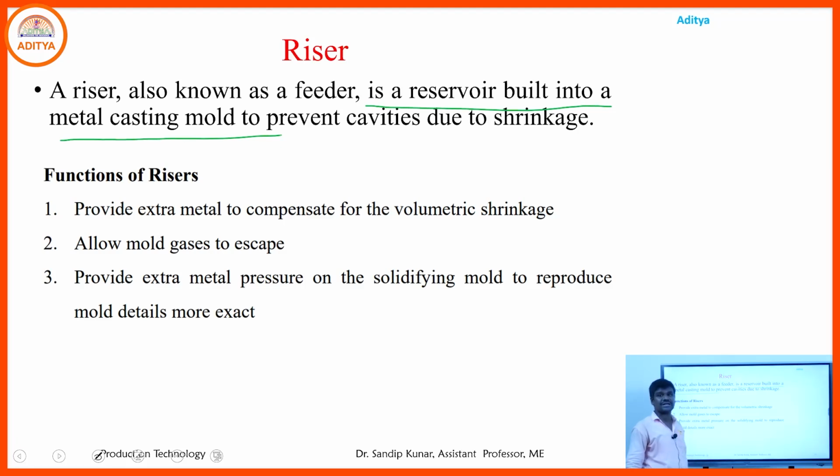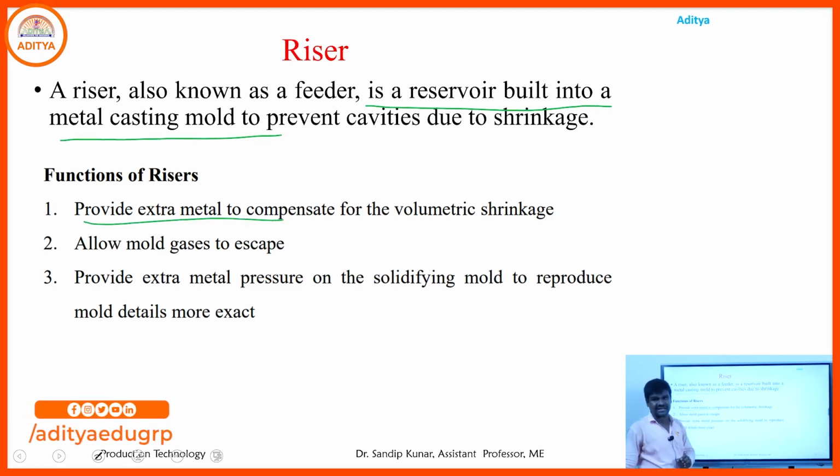What are the functions of the risers? First of all, it provides extra metal to compensate for the volumetric shrinkage. Due to shrinkage, after solidification, extra space is created, and to compensate for that extra space, the extra metal from the riser goes into it.